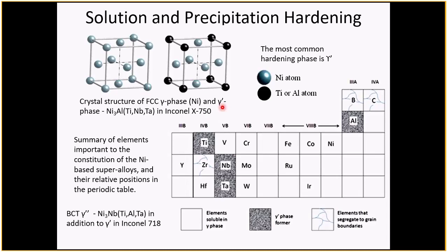So that volume fraction of the gamma prime precipitate isn't sufficient to make the mechanical properties dominated by the gamma prime properties, but it is sufficient to create hardening centers which impede dislocation motion, and therefore give the nickel its high yield strength, or the Inconel X750 its high yield strength. If you remember some of the earlier lectures, if we had a